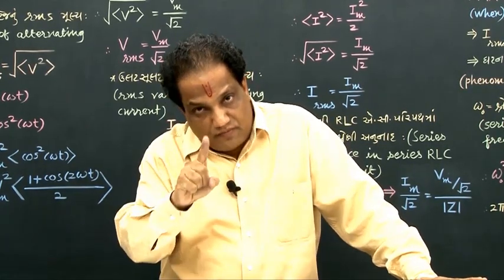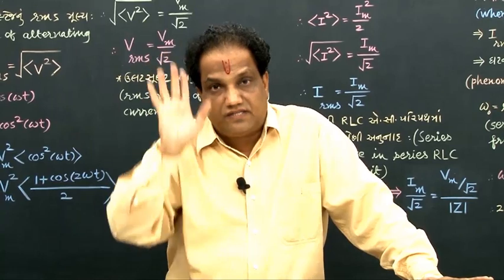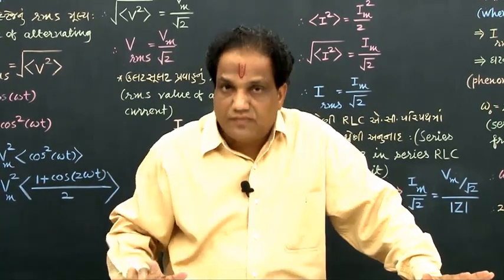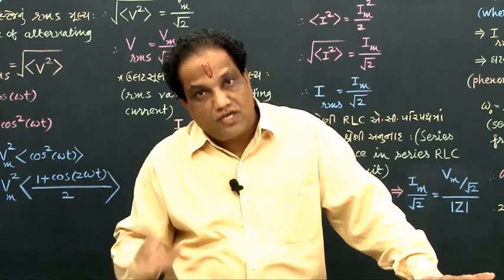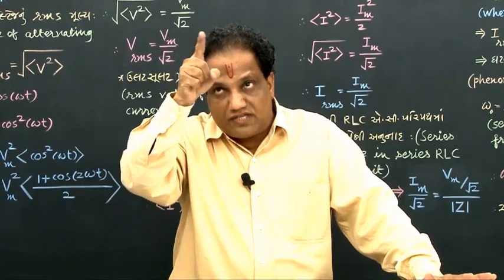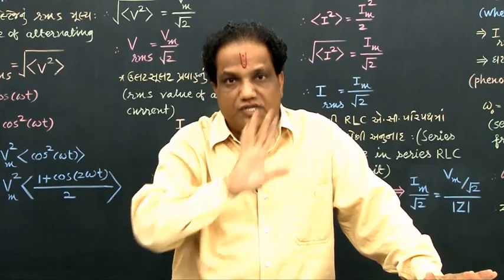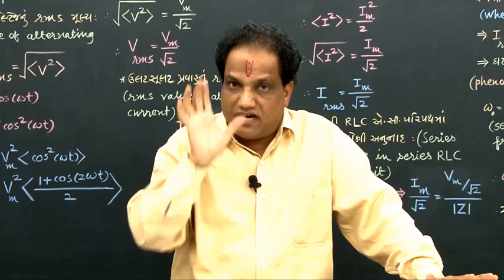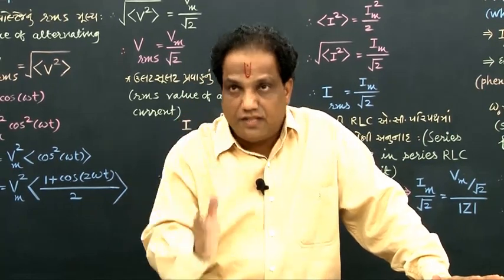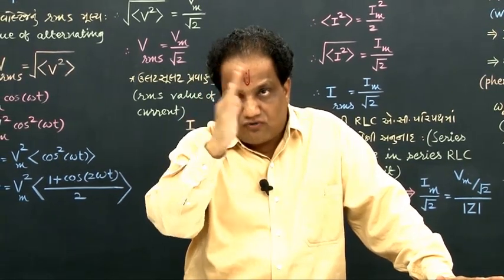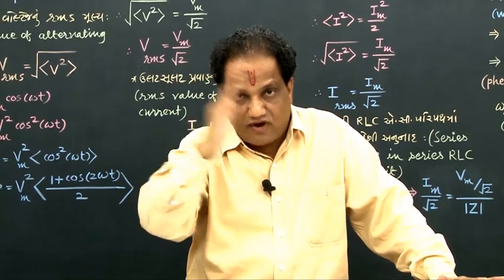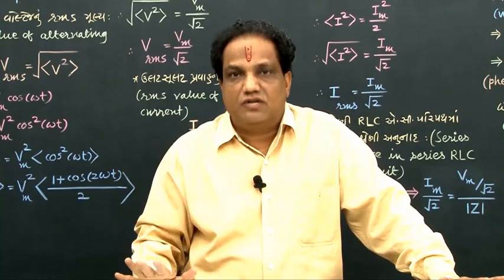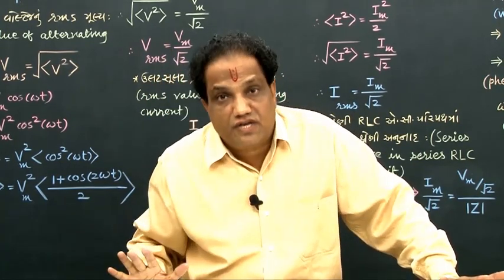If the same voltmeter is connected in an AC circuit, we cannot take any reading, because in alternating voltage, the value and the polarity of voltage go on changing periodically. That's why if you connect that voltmeter into an AC circuit, the pointer would continuously deflect, would vibrate, and will not become steady. We cannot take any observation.